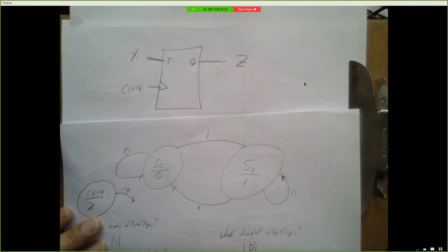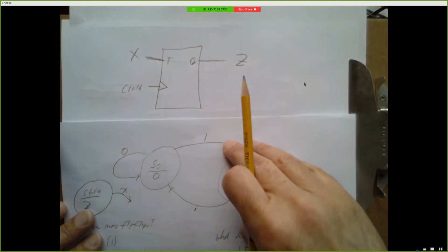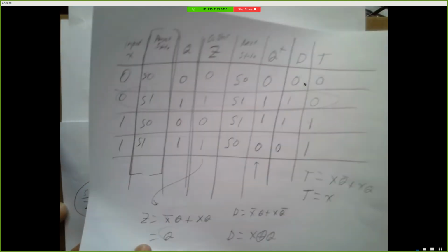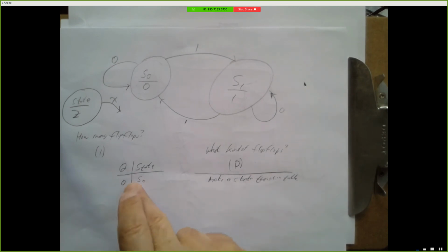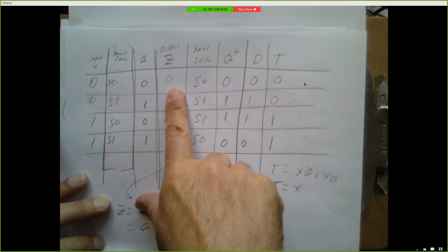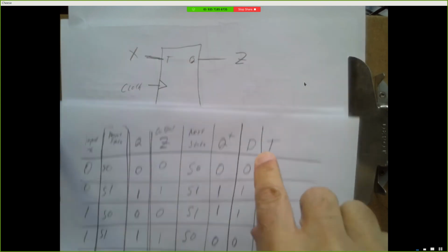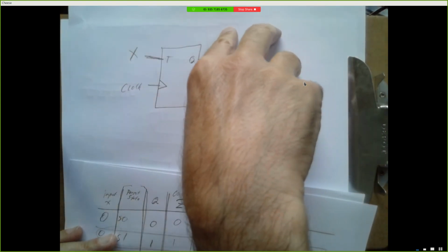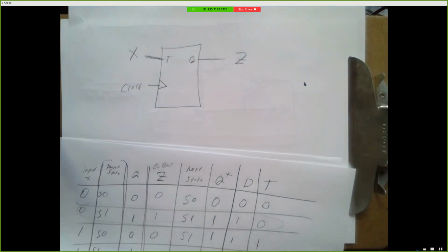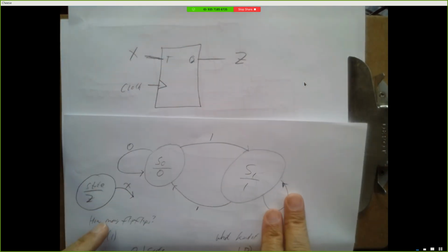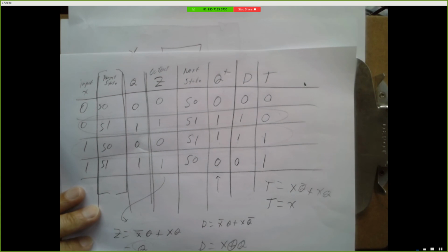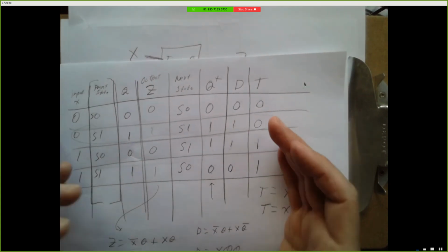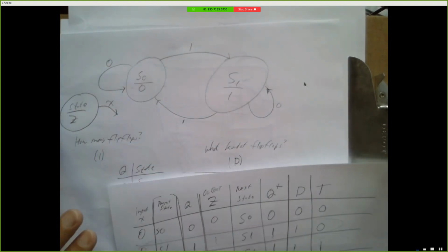So if you come across this example in a book, right, you'd be tempted to think, so why is this a T flip-flop, right? Don't try to figure things out like that. Come back to the systematic analysis, right? Think about this, figure out how many flip-flops you need. If you're going to use T flip-flops, fine, make a state assignment table and start filling in present state, output, next state, how should we set the inputs to the flip-flops. And miraculously, this is what pops out, right? And from that point of the journey, you can start to look back and say, okay, so why is this the thing that corresponds to that, right? And try to find meaning in it. But all of these problems, right, are done by doing this very systematic, very procedural, algorithmic process, okay? So if you know how to do this, you can take any of these diagrams and come back and work your way through it.